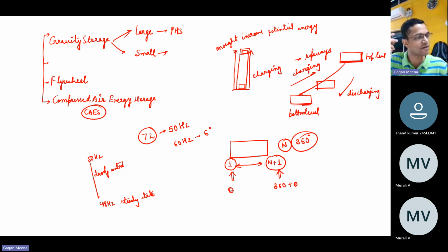Because when we consider only droop, we are not considering the limit on generation. A limit on generation has not been considered, so these equations will not ensure that the generator is at its limit. We only have three equations: one is summation of generation equals load, and the other two come from the droop characteristics. These equality constraints do not ensure that PA will be between 0 and 200 and PB between 0 and 400. The data may be randomly given. Yes, it is because of the data.